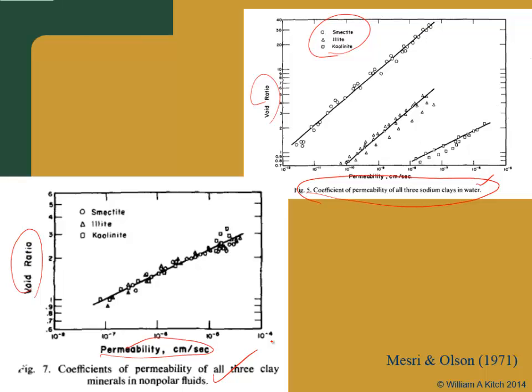Now, I will point out that's still to a log scale. It's a semi-log scale. I'm sorry, it's a log-log scale. And log-log scales cover many, many sins. When you take things and convert them down to log-log scale, you eliminate a lot of variability. So there's a lot more variability than might appear there, but that just shows you how important surface chemistry is to hydraulic conductivity of fine-grained soils. And pore chemistry. So in a lot of the geoenvironmental issues, clay liner behavior and such, that pore chemistry is really important, and it can dramatically change the hydraulic conductivity.